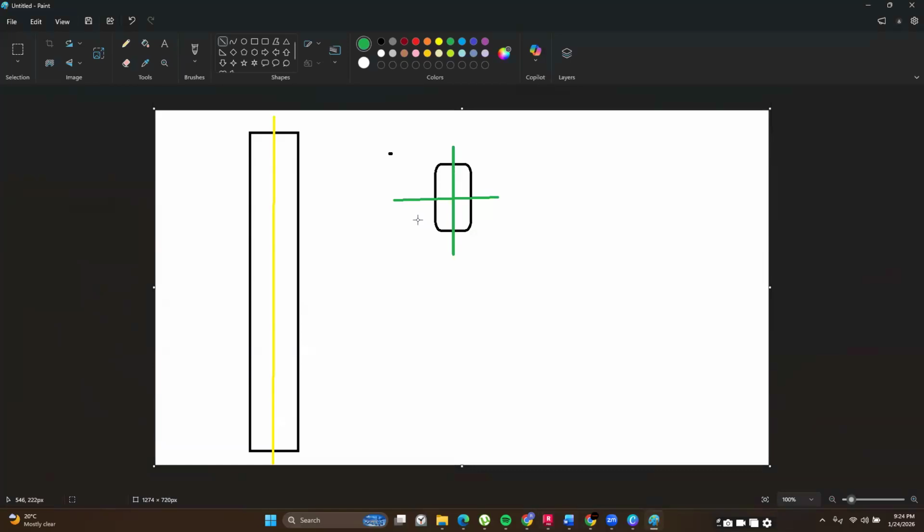So I'll bring you back to something I explained yesterday, or what I was advocating for during modeling: that you stay consistent with the direction along which you model your slabs. If you choose to go from left to right, stick with that, because the direction you start modeling with becomes your x-axis, and the second one becomes your y-axis.